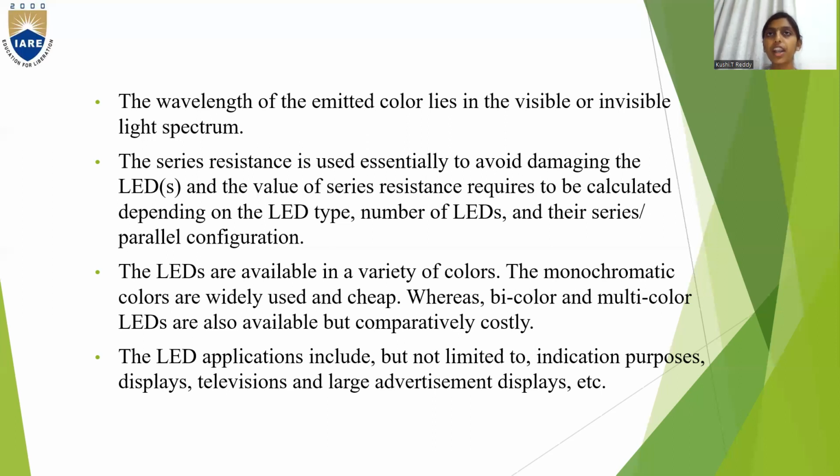So the main point is that an LED converts electrical energy into light energy, and an LED is always applied in forward biasing, and the current is always allowed to move in the forward direction, and the current which is moving in the reverse direction is always blocked. And coming to LEDs, you have different varieties of LEDs which emit different lights depending upon the particular spectral wavelength.